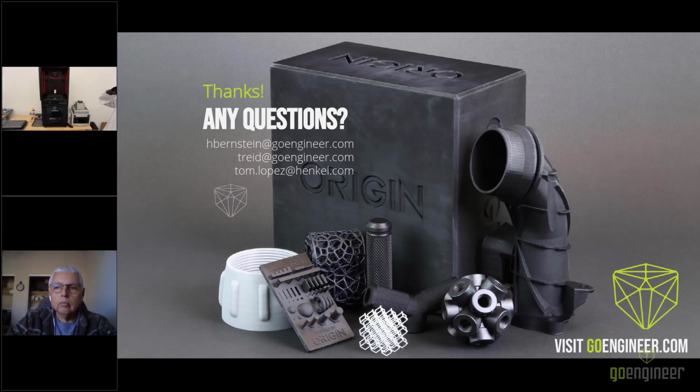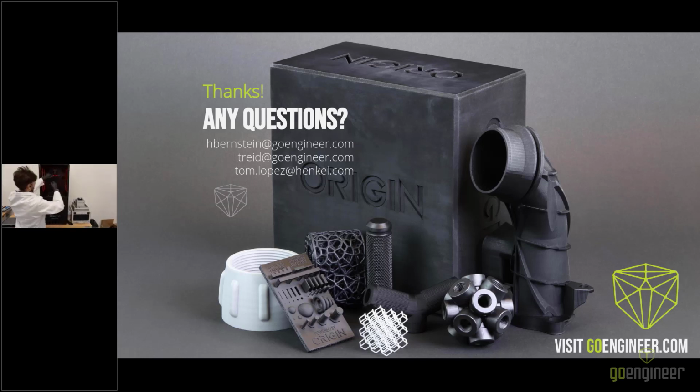Well, in case anyone has any more questions, I'll let those trickle in. But I do want to show just how easy it is to get up and running with this machine. Right now, I'm removing the part that was just printed. We'll bring it up on camera for everyone to see. These parts are covered in resin. I need to knock them off the build plate, wash them, let them dry, and then they can be cured.